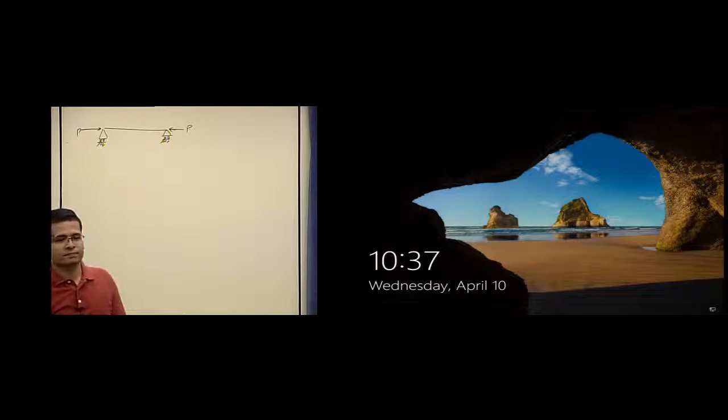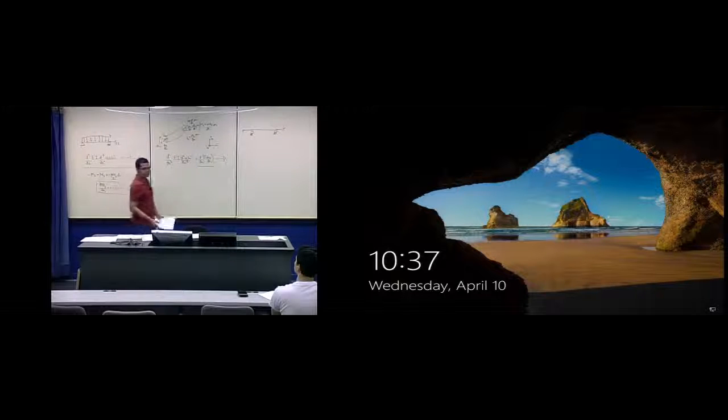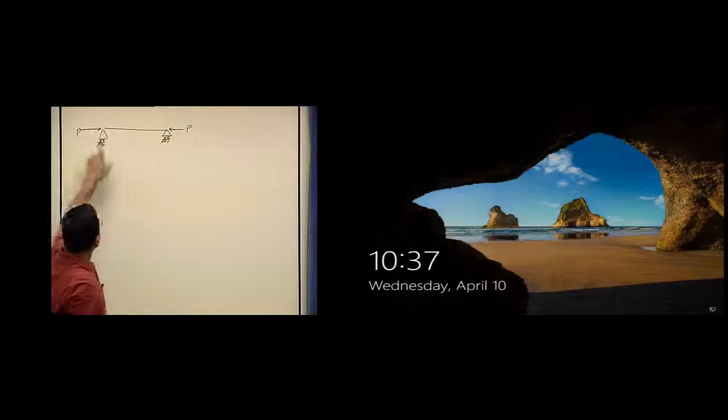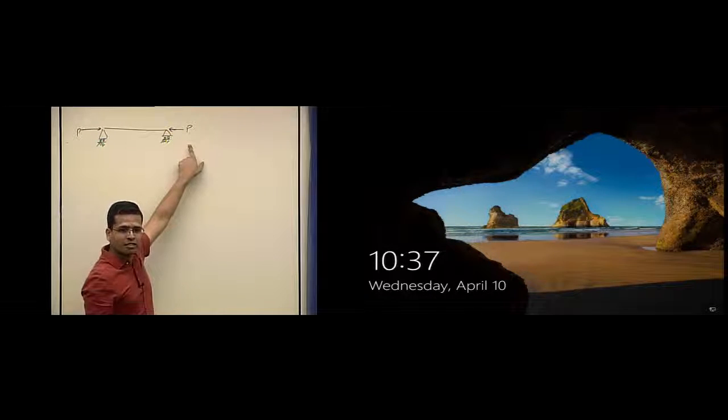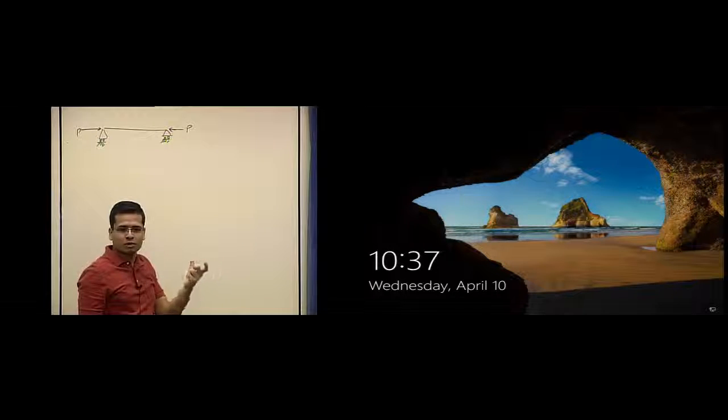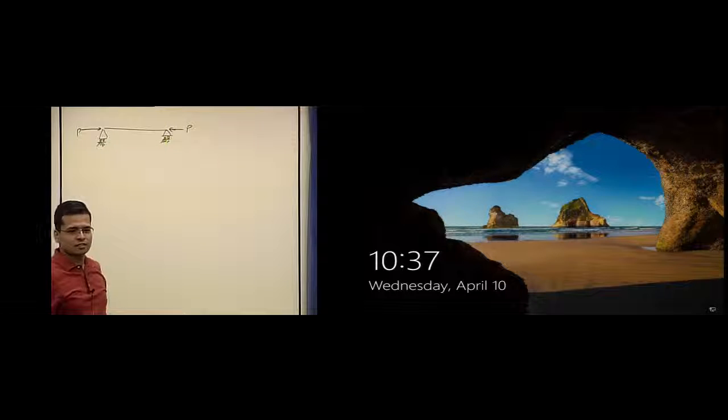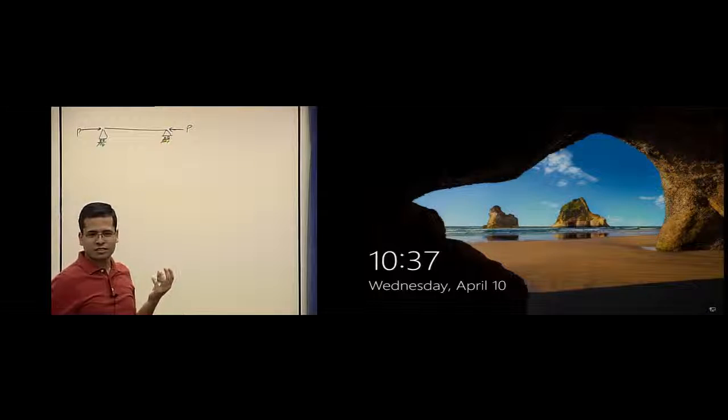Is it simply supported because there are two rollers? Yes, I actually wanted you to point out that here there is no point of having this P, but nobody did that. So it is a simply supported beam, and there are two rollers because this P is applied at both ends, so this will keep the beam in equilibrium. It will not let the beam move in the axial direction. So essentially what simply supported does is prevent displacement. Exactly, yeah.